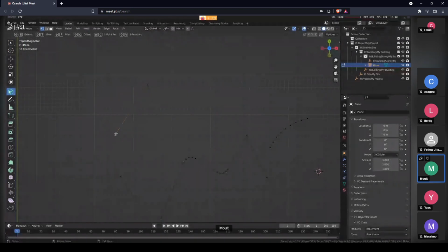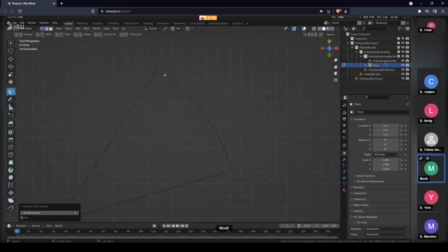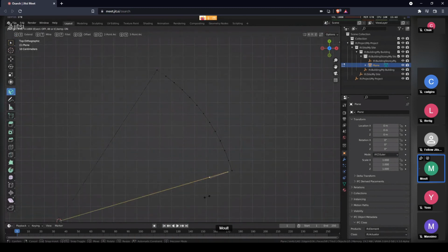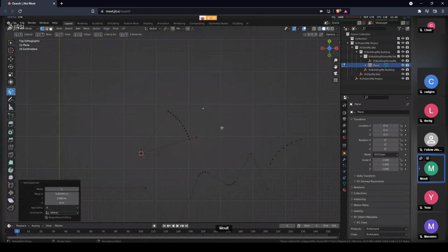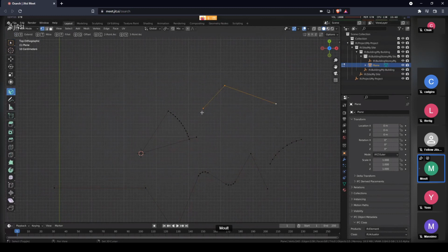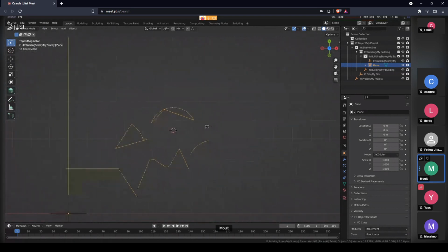So in fact, I'll just do a quick example here. That's two points. We'll say this is the third and do a two-point arc, and there you go. This is the arc which intersects with that line, wherever that line happens to be. There's also a three-point arc, which is pretty obvious, as the name suggests. You take three points and you get your arc from that. They're all circular arcs.